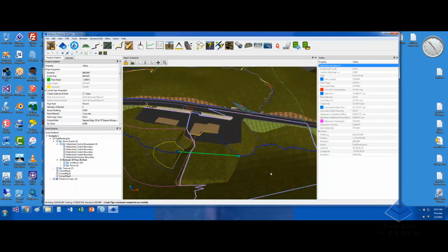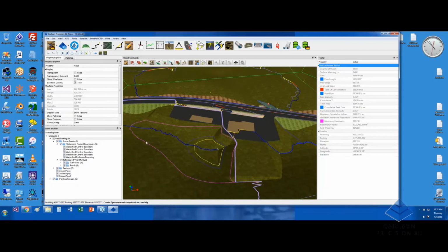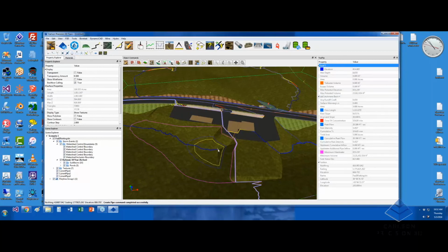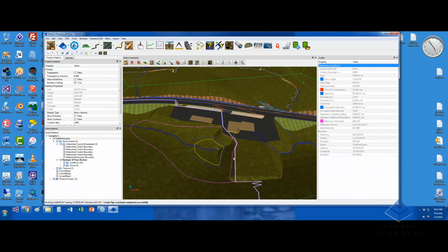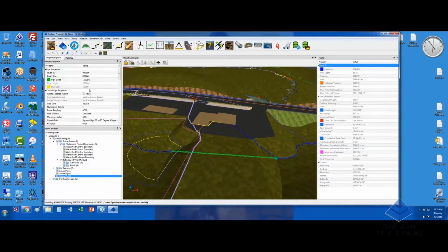And you're going to see the headwater. So basically what you're seeing now in this pond, this magenta line represents the maximum topological bowl, as much water as this thing can hold without spilling over. During the peak of this particular 10-year storm, the blue outline is the maximum depth that this pond will reach during the storm without the culvert pipe. With the culvert pipe placed, this yellow headwater represents the maximum depth that the water will rise up to if we use this particular size culvert pipe, which is 3, and it's an 18-inch pipe. So we can modify it.